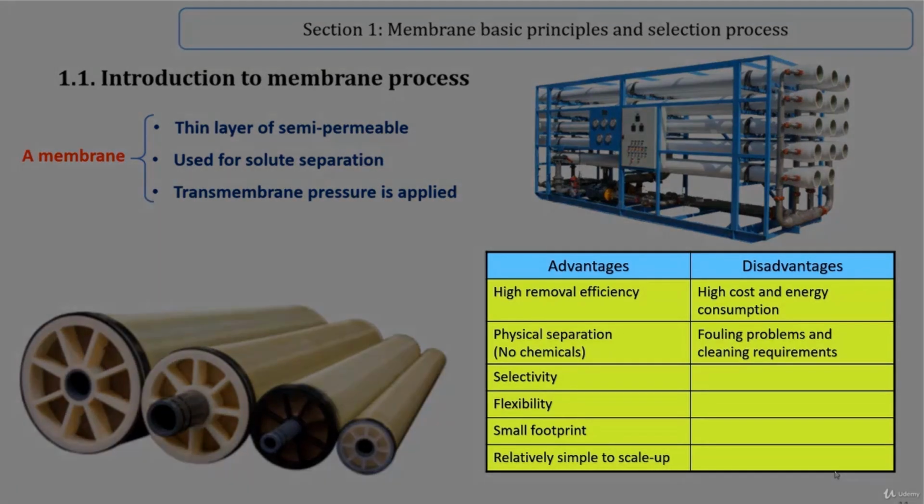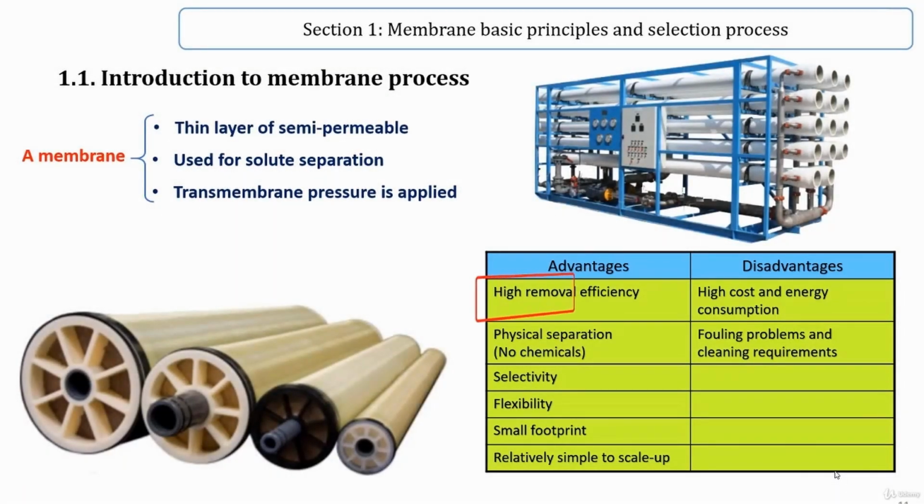Let's look at the main advantages and disadvantages of membranes. Some advantages such as high removal efficiency. Membrane technologies for water purification are exceptionally attractive due to their high efficiency. Physical separation. One of the particular advantages of the membrane separation process is that it relies on a physical separation, usually with no addition of chemicals in the feed stream and without phase change, because adding chemicals may cause problems such as interactions with constituents or residual removal may be needed.